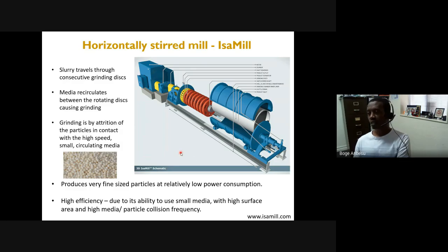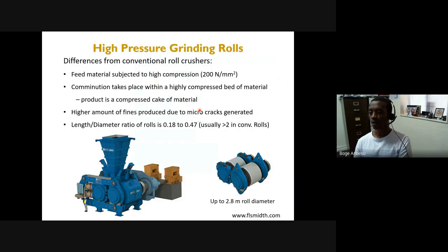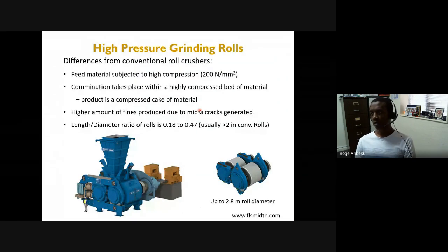Okay, but again, these are some of the recent technologies or advancements in comminution. So again, there's a bit of a controversy. Some people don't want to say this is a comminution stage, but in these places, obviously, it is a comminution stage. But in many places, you can also find this kind of mill as a regrinding mill. So you do your ball mill, you separate the fine from the coarse. The coarse ones can be reground and put back in the mill. Okay, so for those purposes, you can use them for regrinding as well. But you can also incorporate them in your grinding circuit.